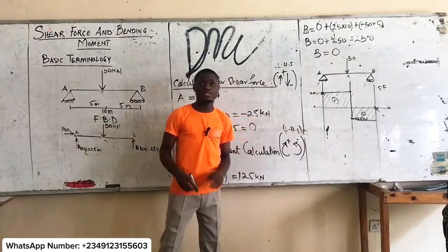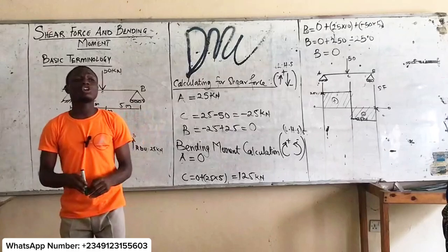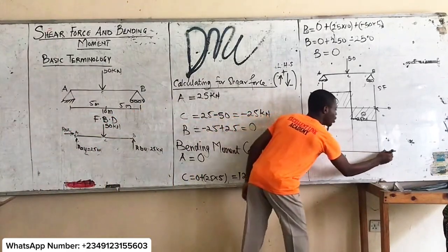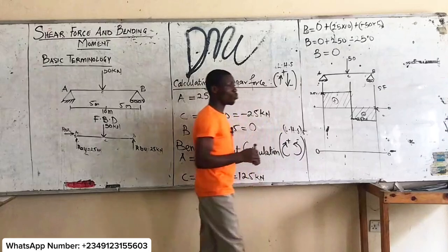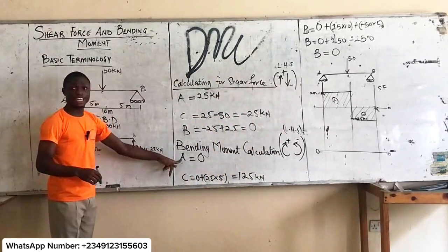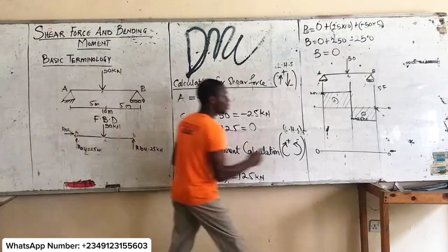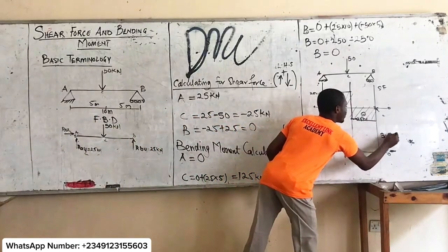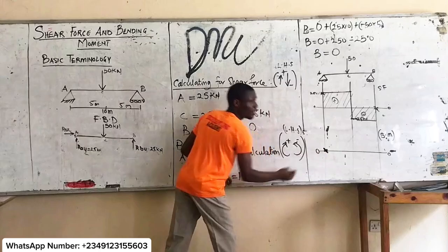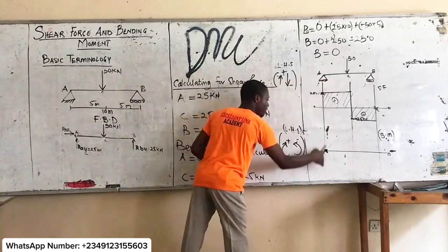Let's bear in mind this. Bear in mind always what? Below what? Your shear force. So let's take another region here, region O. Now, please check your bending moment. This is the bending moment. At point A what is it? 0. Yes, 0, Abi. At point A, that's 0.